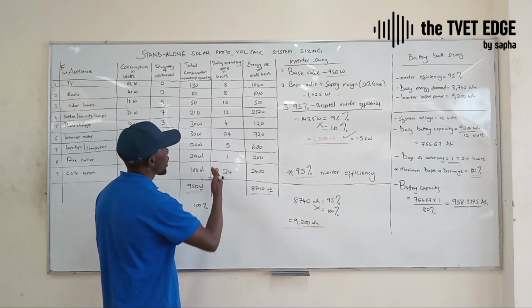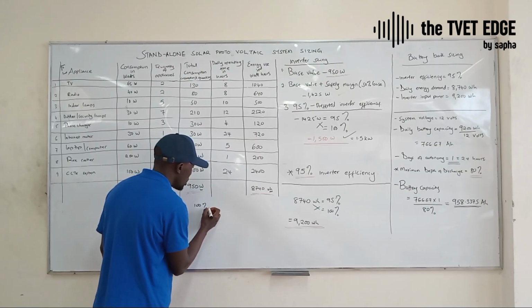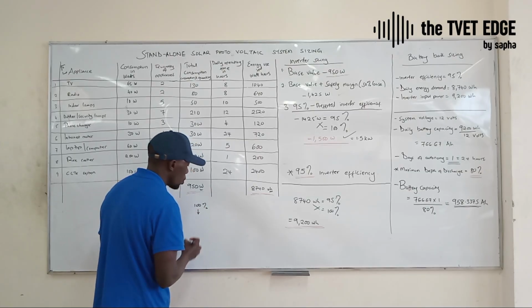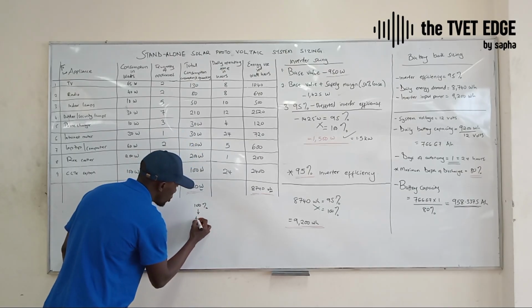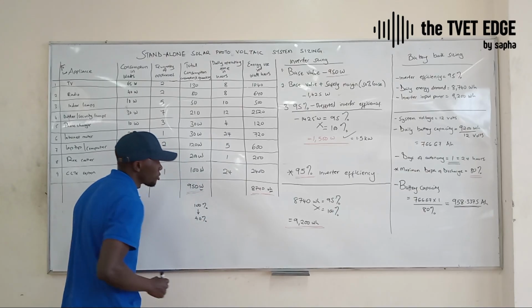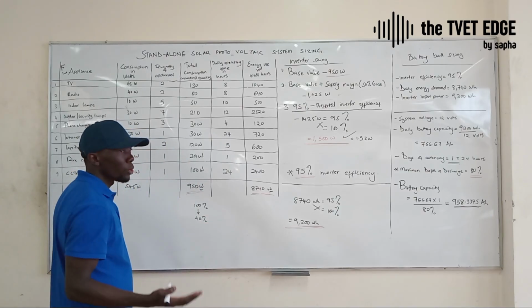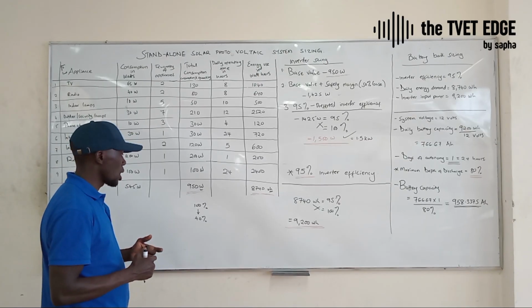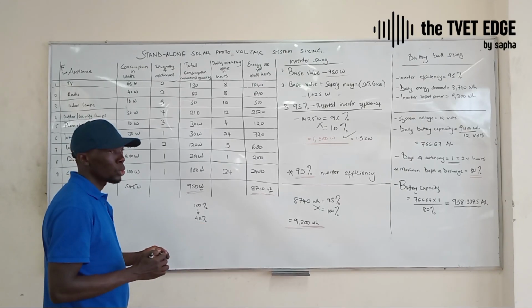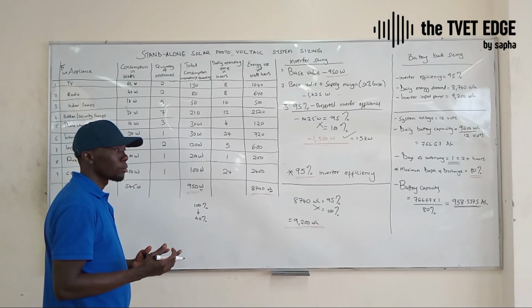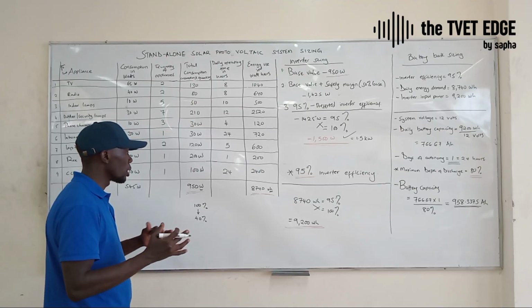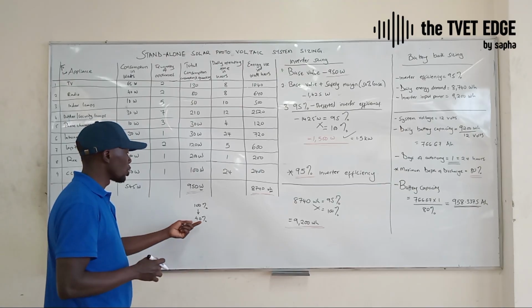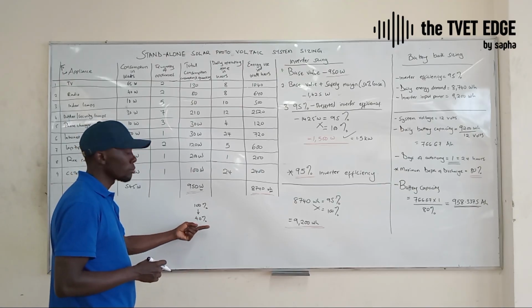Overnight, you plug in your appliances and they drain that battery to, let's give it a fair value, 40% state of charge. You can find this figure probably on the inverter. Some inverters have been programmed to give you this value, so it will look at the voltage and other variables for it to tell you at what percentage this battery is.